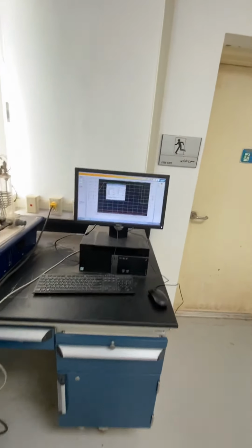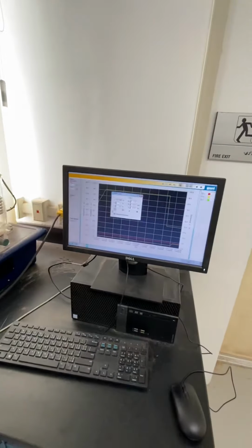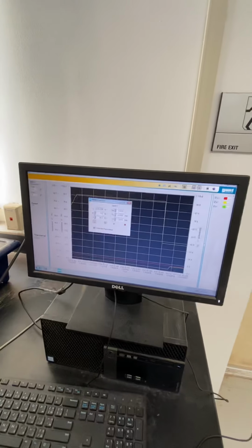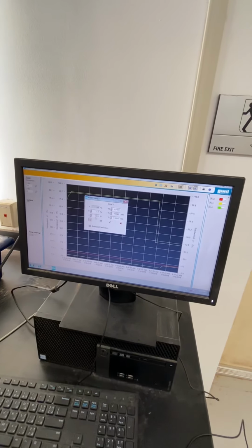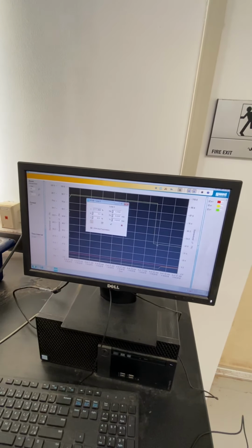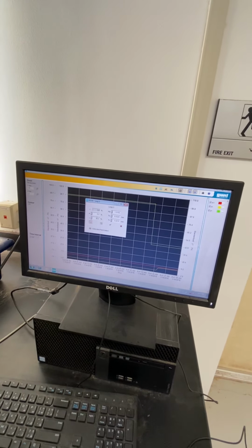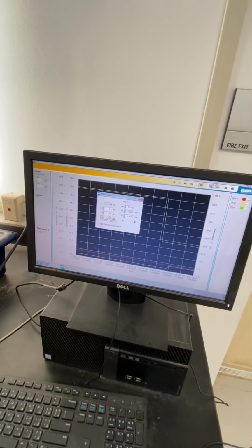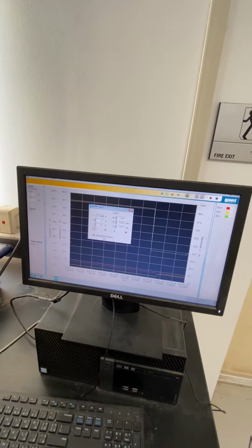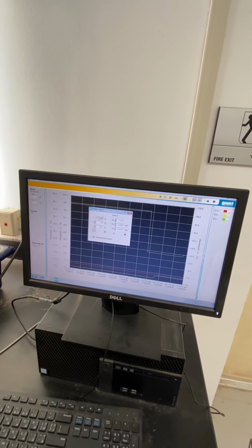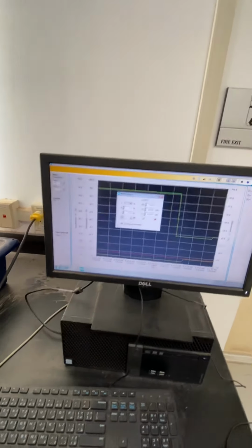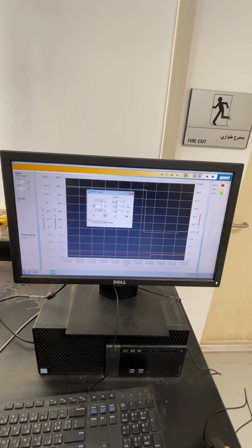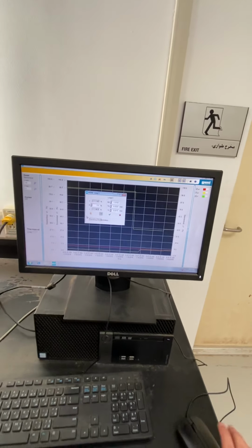And you can see right now, guys, that once the problem has been fixed, the process value is showing now 4%. I am in the manual mode. I'm running the system manually. So I will bring it back again to the automatic mode. I will just slightly increase the output signal like so. And then once the process value becomes so close to the set point, it is now completely safe to switch to the automatic mode.